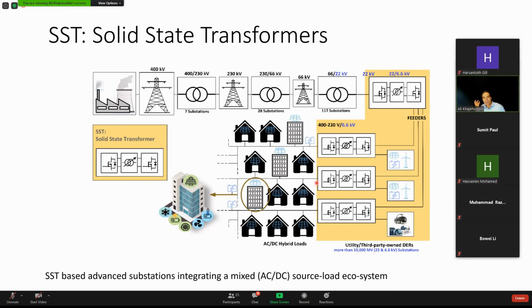And now that we have power electronics, we can actually use the advantage of DC. And many of the resources that we have, renewable resources, directly generate DC, like fuel cells, the battery, the PV panel. They're all generating DC. So when you want to connect those to an AC system, you need this extra stage, which means extra losses, to connect them to AC.